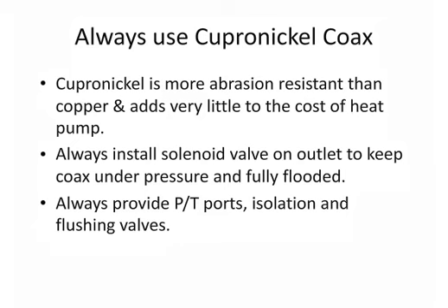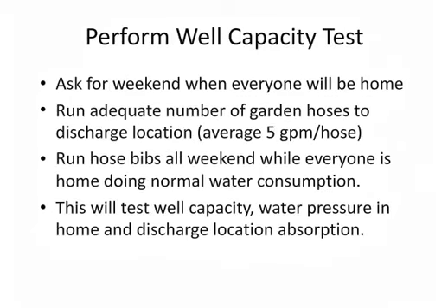Always, always, always install pressure and temperature ports, or Pete's plugs, isolation valves, and flushing ports. You're going to see that coming up here. Perform a well capacity test. This is something I did very often. I asked them when everybody was going to be home. Again, retrofit application. If I was going to put in a 3-ton and it was going to run at 6 gallons a minute, I would run probably 2 garden hoses, assuming I'm now running about 10 gallons a minute, and sometimes it could be even 12 or 14, depending upon that particular water system.